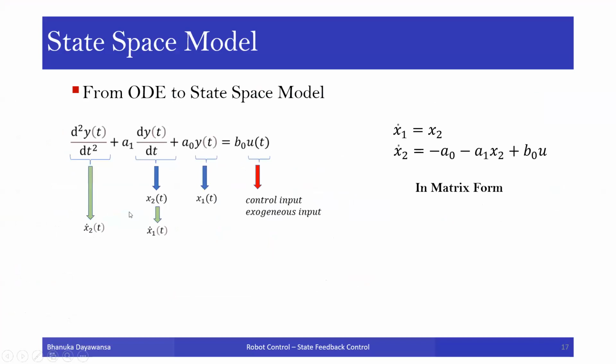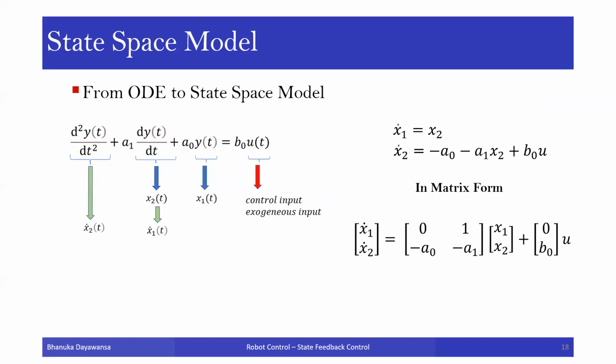So basically, if you write this in matrix form, you get this, right? It's a differential state space model. So simply you stack them up. So this x1 state equation is this one. So there's only x2, so one coefficient there. No control input, 0. x2 dot: minus a naught times x1 here. Minus a1 x2 is here. And now here there's a control input.